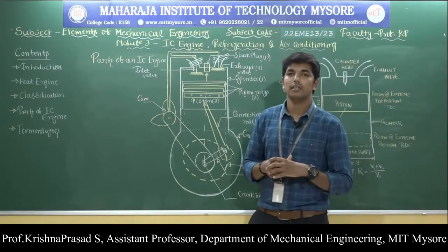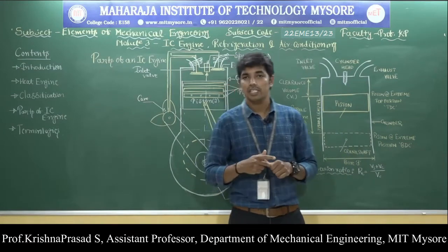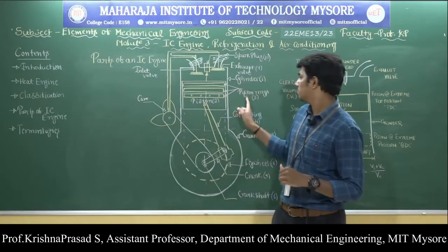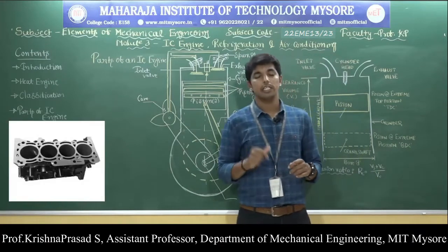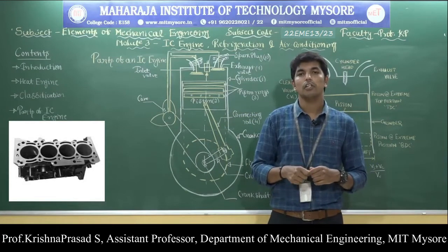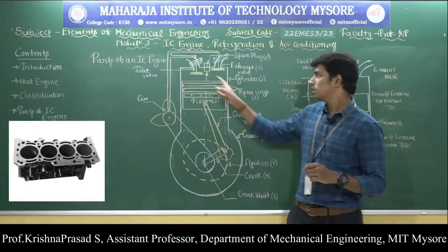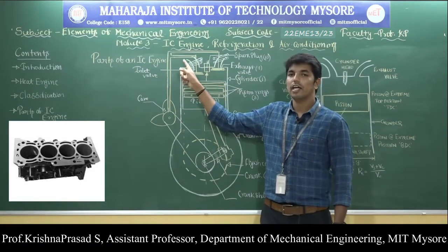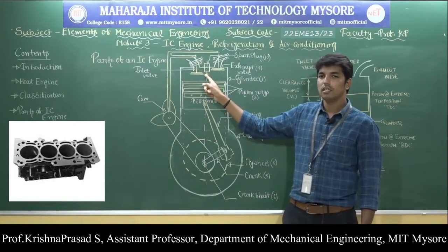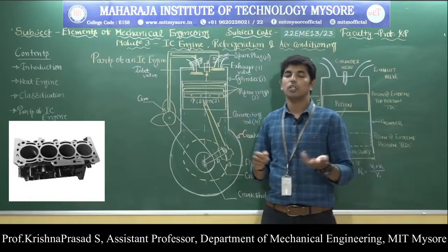These are all very important before going on to the working of an IC engine. The very first important part of the internal combustion engine is the engine cylinder. What is meant by the engine cylinder? The engine cylinder is the heart of the engine in which fuel burns and power is developed. In the suction stroke, the air fuel mixture enters the engine cylinder through the inlet valve, so that in the power stroke the spark plug ignites and power is developed.